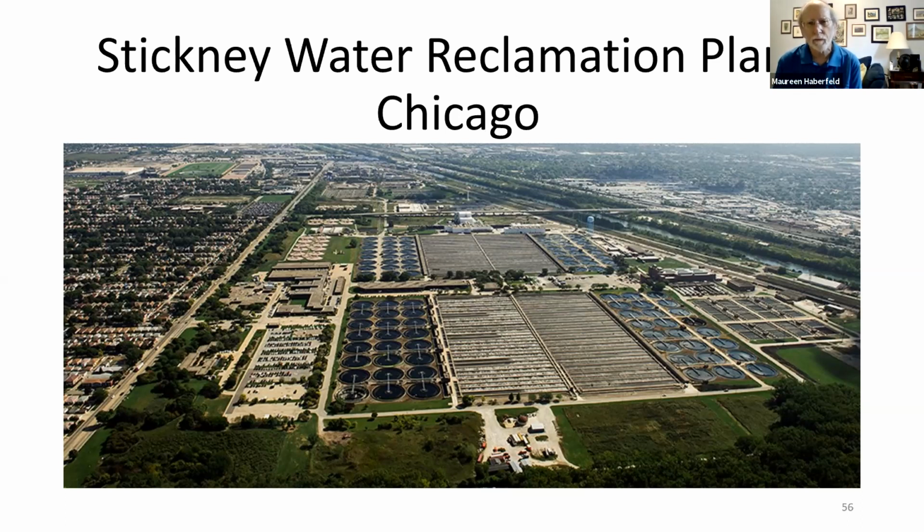During times of extensive rainfall, this plant, as well as all other domestic wastewater treatment plants, will have a lot more water coming into the plant for treatment. It's stormwater. It gets into the plant normally because of breaks, holes, imperfections in the transmission lines that take the sewage to the plant. During periods of high rainfall, some groundwater gets into those transmission lines, or maybe there are storm sewers that feed the plant. This is stormwater runoff.